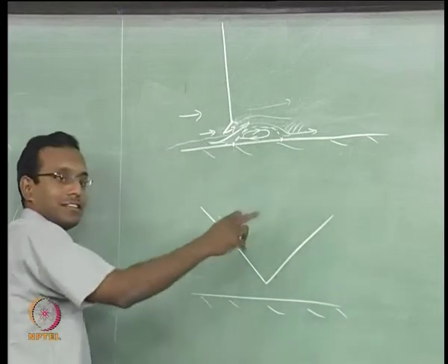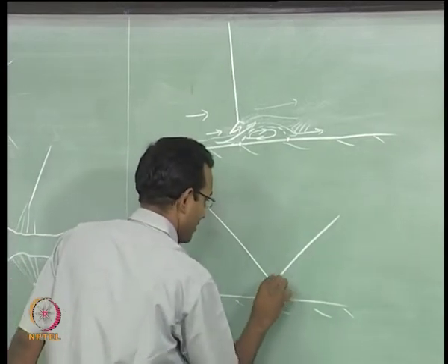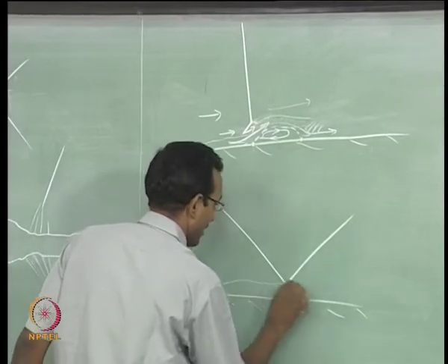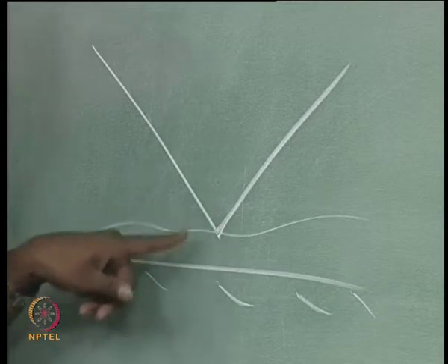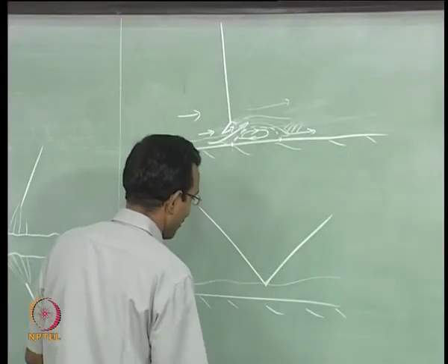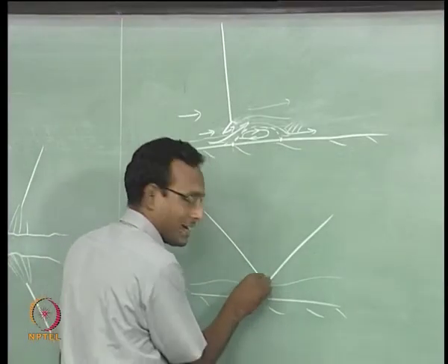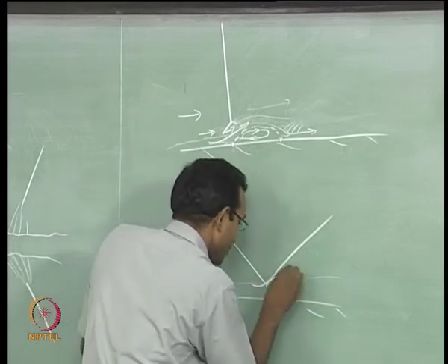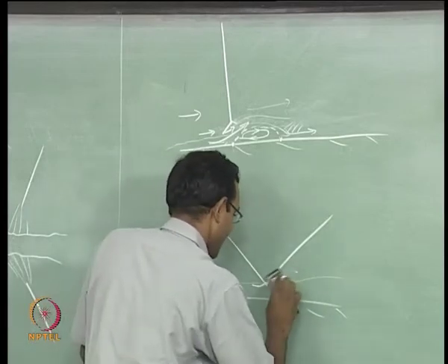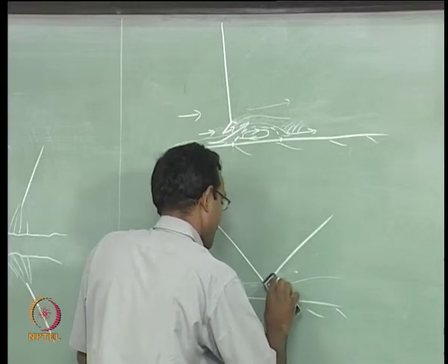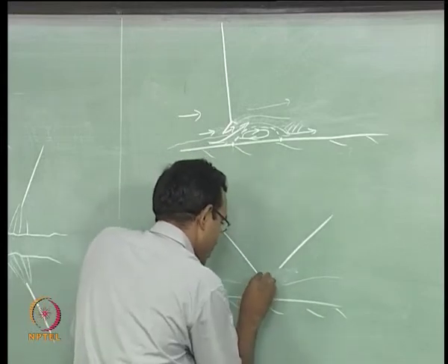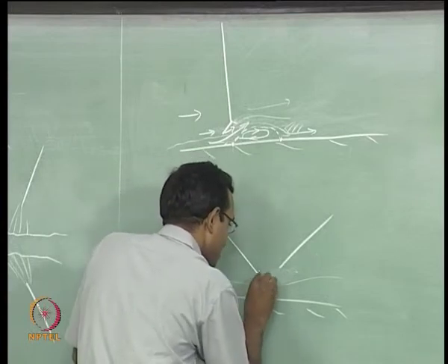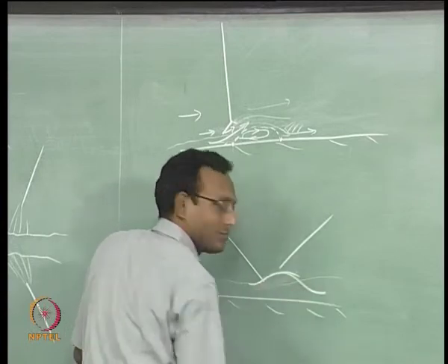If I consider something like this, and I am going to have a boundary layer. I am drawing something like this, but I am going to change this picture immediately after this. What it is going to look like is, when this shock comes and interacts with this, the boundary layer is going to do this. The streamline in the boundary layer will suddenly jump up. I will erase this local region. Going to come here, and suddenly this streamline will jump up and then go back down.